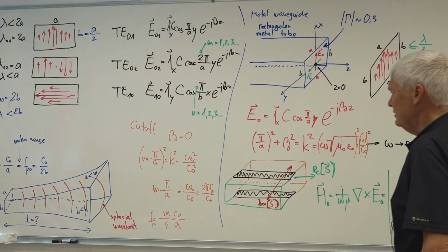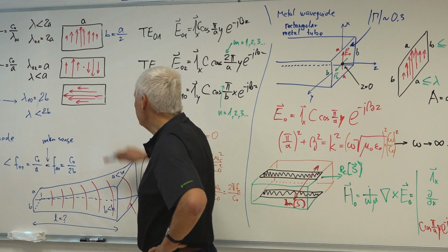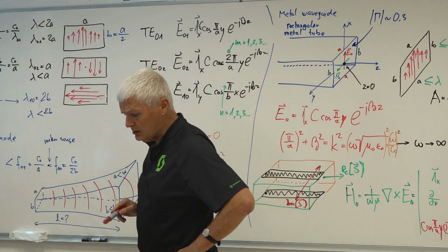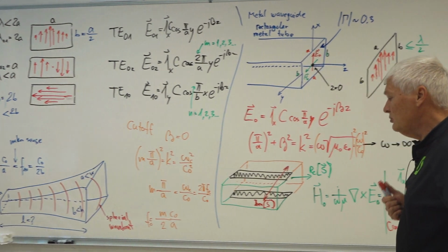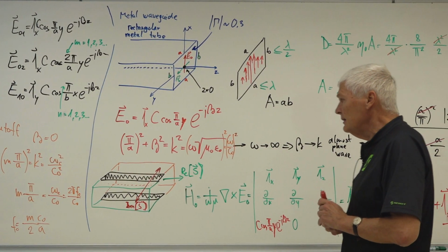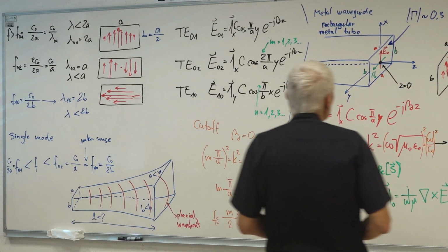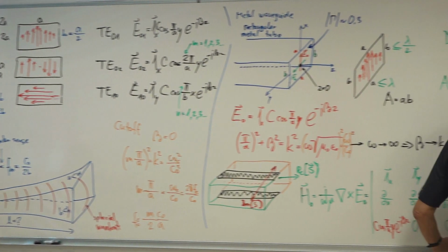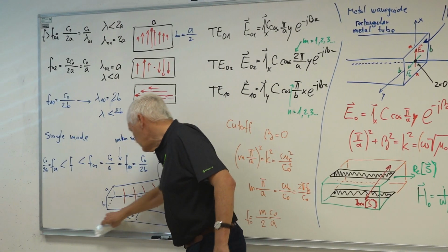How to avoid errors when wavefronts are spherical? Spherical wavefronts could be represented also by higher order modes. But I need to make the horn in such a way that these wavefronts will be flat here. Okay, what is the condition now here? Well, we already had the Rayleigh distance as the condition.